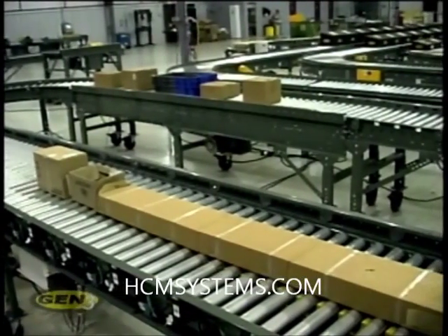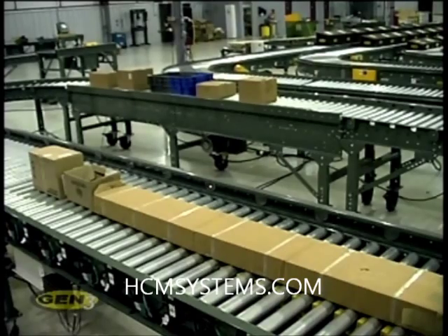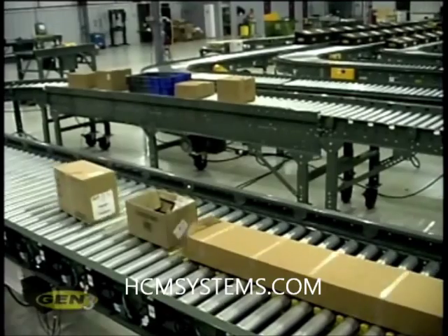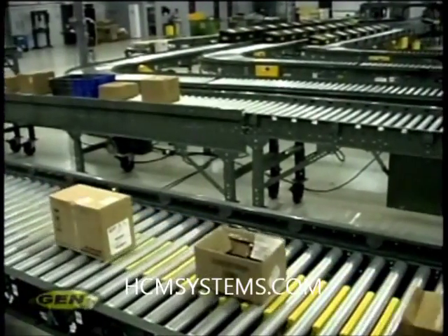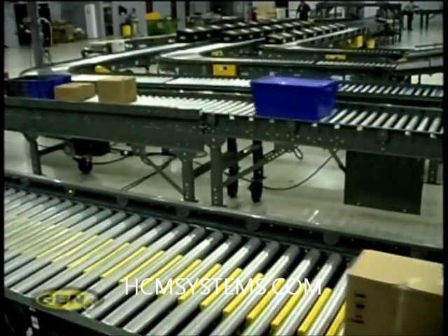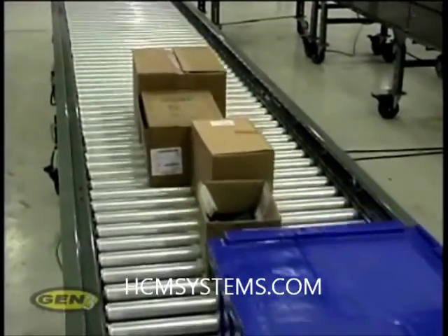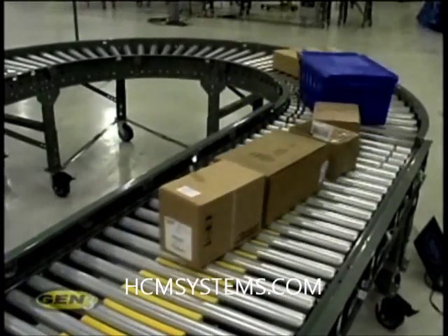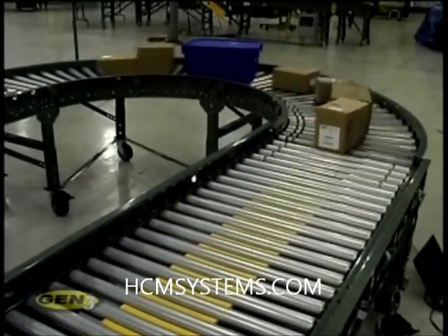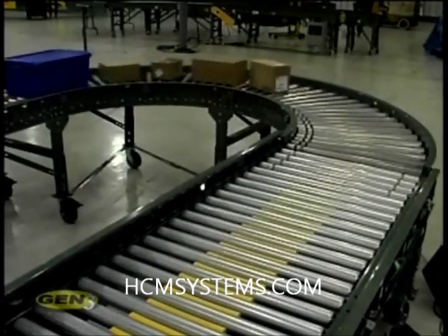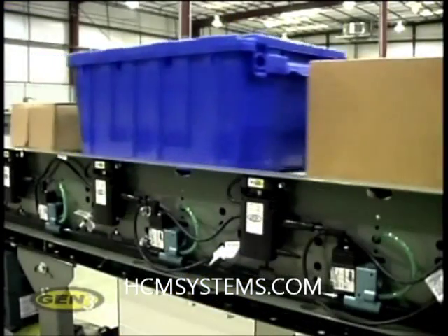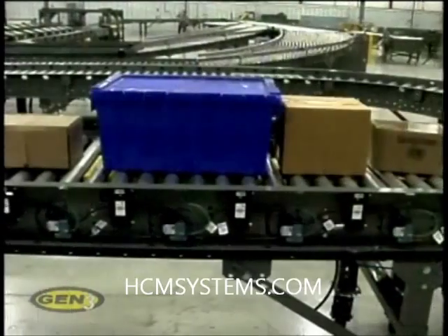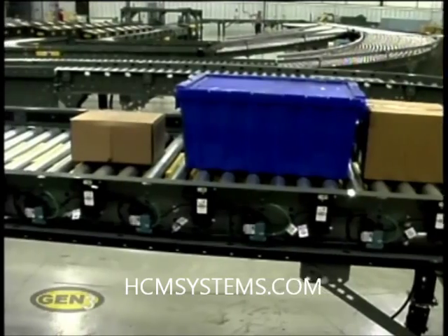Dynamic zone allocation technology ensures that longer cartons introduced into the system after installation do not obsolete the system. By only assigning longer zone lengths when needed, dynamic zone allocation increases carton throughput, accumulation density, conveyor efficiency, and system flexibility. When individual carton control is not required, slug mode may be used to provide dense accumulation and high throughput. Cartons are not separated when traveling down the conveyor or when they are released from the conveyor. Zero pressure is still provided during the accumulation cycle, but only as the cartons arrive at the proper stopping point.